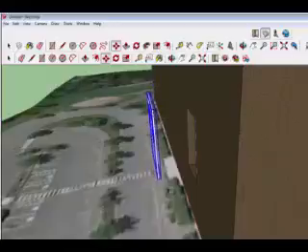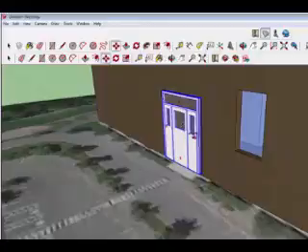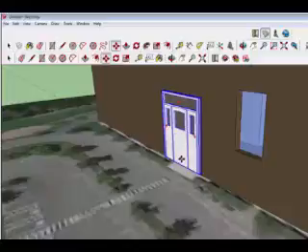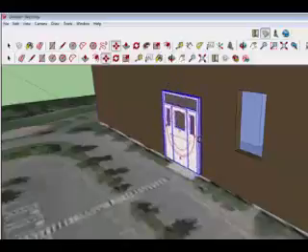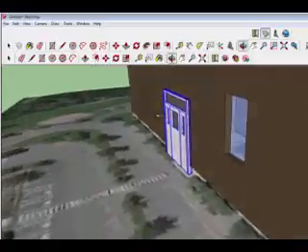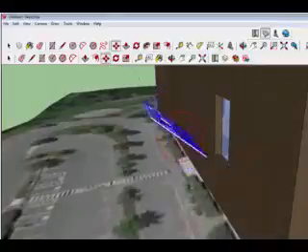Now to spin it, sometimes they come in out of spin. The easiest way to do this, I found with the kids, is if you click on the move tool, you'll see the little red dots, and it turns into the protractor, the circle arrows. If you click on that, it will spin on that point. So if I want to spin the front, that's how I can do that. And then I'm going to turn sideways and click the move tool, and you'll actually see these two points. That's how I could spin it.